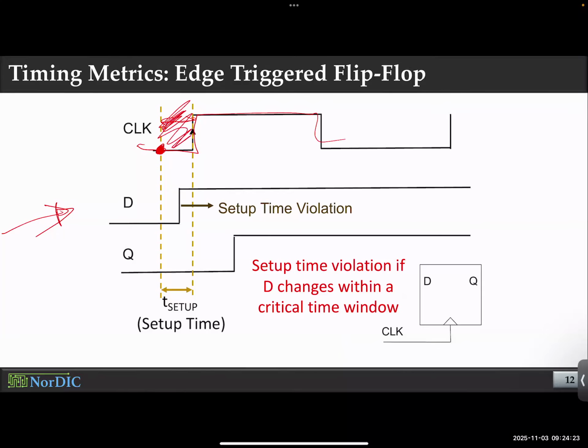This is your setup time window, right? Within this time, the flip-flop needs its own rest. It doesn't want to take any kind of input changes. However, your input changed in between the setup time. So we are showing that this change was reflected, but it may not be reflected. We don't know. It may or may not be.